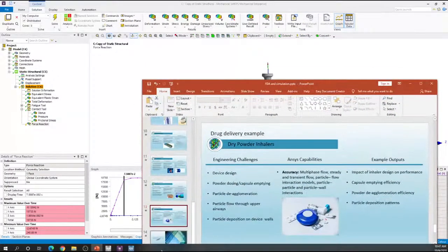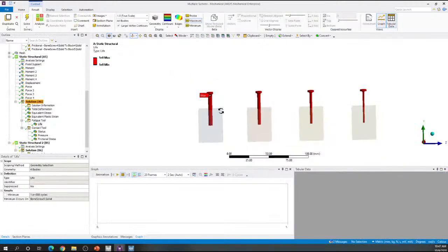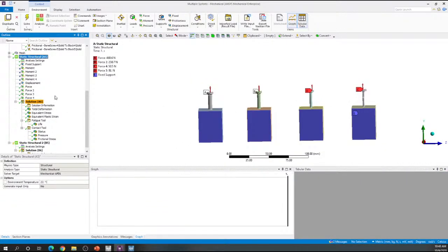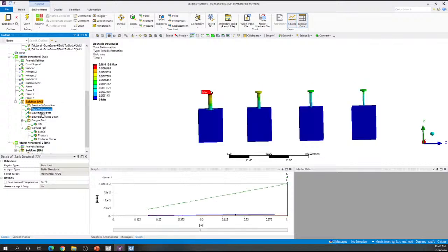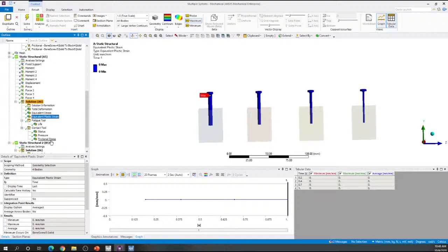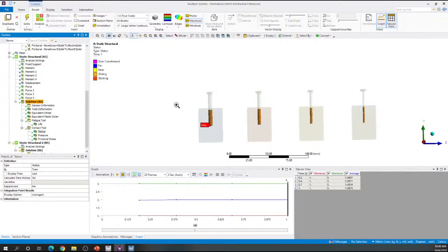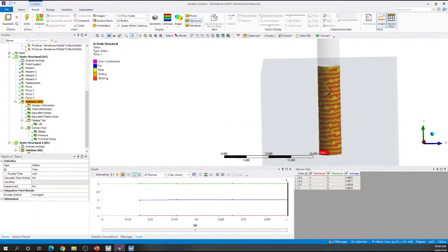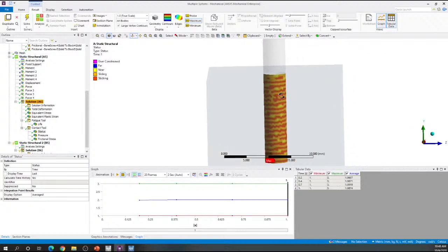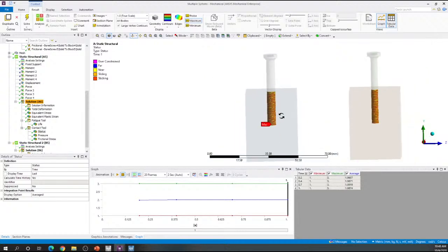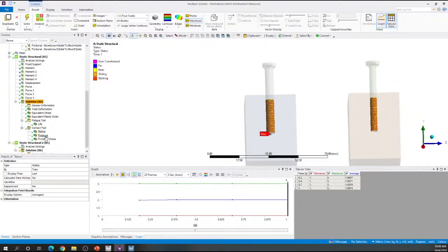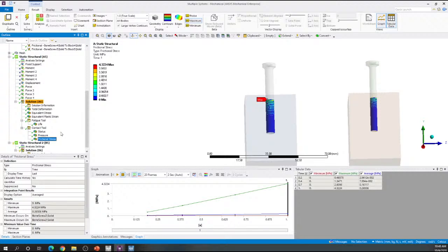And then I showed you a quick example of how you can do a quick comparison between 4 different bone screws according to the criteria laid out by the FDA. We allow you to compare deformation, stress, plastic strain. For screws in particular, ANSYS has all kinds of these nice features. We can model the threaded contact to make an accurate prediction of where stress concentrations will occur and what the forces, pressure, and frictional stresses are in the model.